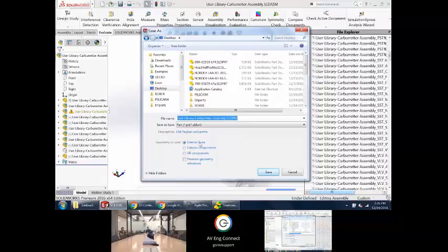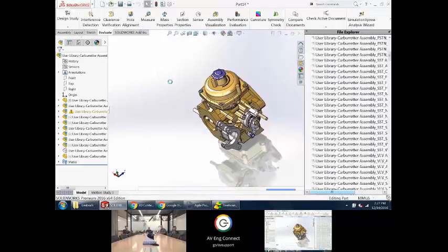This one is terrible. What exterior faces does for you is every face on the outside of that is going to be its own surface body. So you can end up with like 1,000 surface bodies in the part. Also, when somebody wants to make a change, like, hey, can you drill a hole through this? No, you can't drill a hole through surfaces. You need to trim body on every one of the surfaces and then put a cylinder in the middle of them to make it look like a hole. So don't do that, please. Do this one. When you say, I want to save it with all components as a part file, do that. Probably will take a little longer.